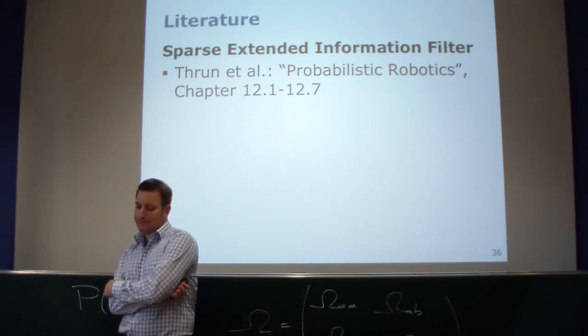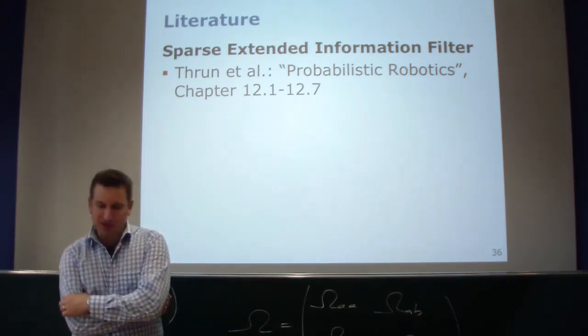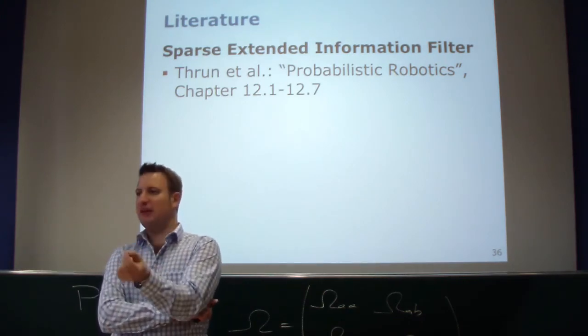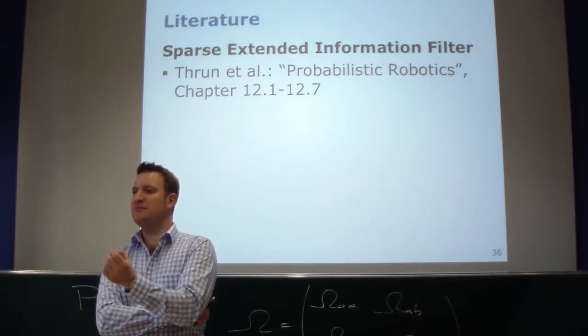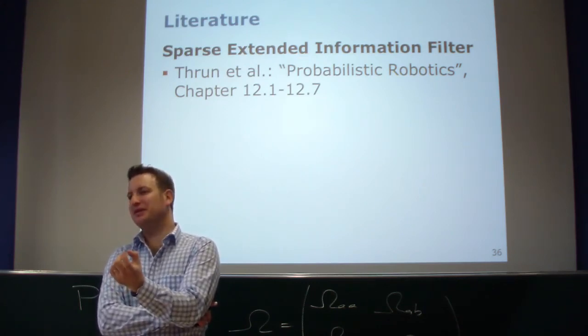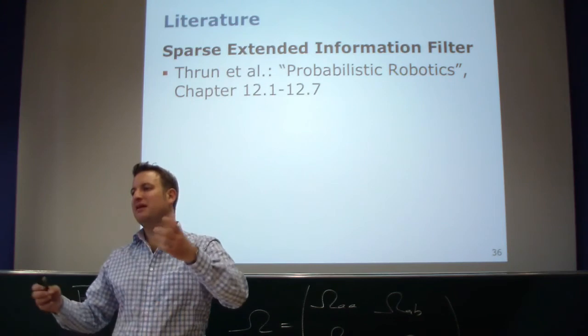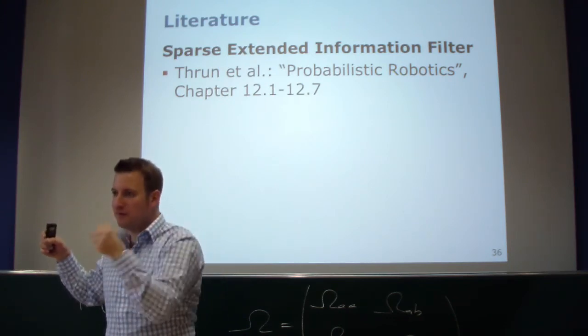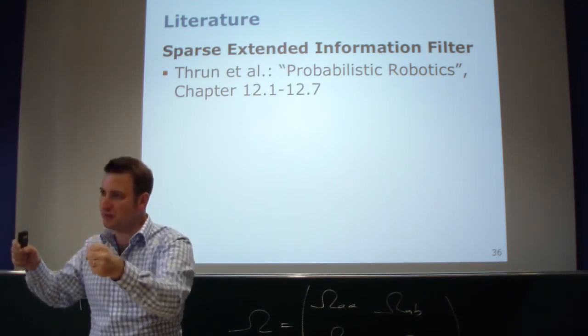So the question is, what do you define as a better map? If you define the better map as the displacement between the features in the map and where they are in reality, adding more features shouldn't really help you here. Because in the end, if you even think of the EKF, they are all correlated. So if you move one feature a little bit in one direction, all the others move as well.